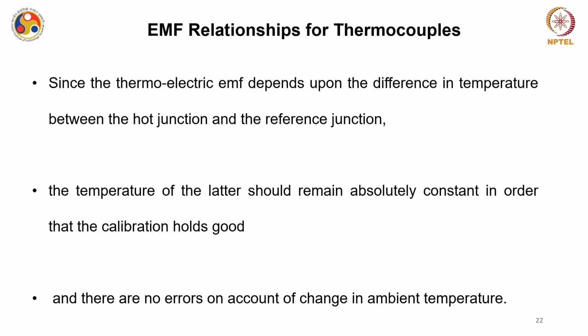Since the thermoelectric EMF depends upon the difference in temperature between the hot junction and a reference junction, I am now not using the term cold junction. Cold junction means the junction where the temperature is less. I am calling it a reference junction. So now I have two junctions, a hot junction and a reference junction. The temperature of the reference junction should remain absolutely constant so that the initial calibration will persist over the years of operation of the thermocouple.